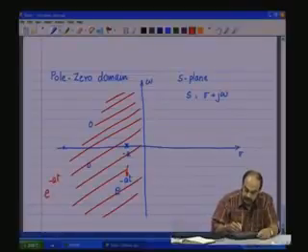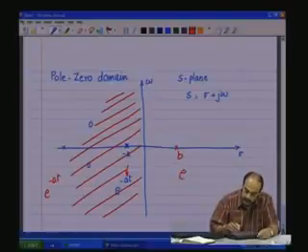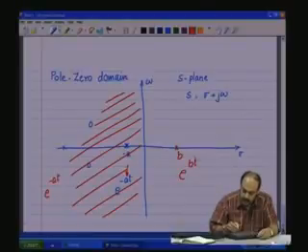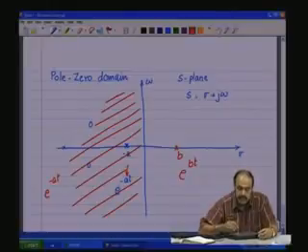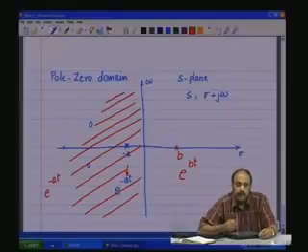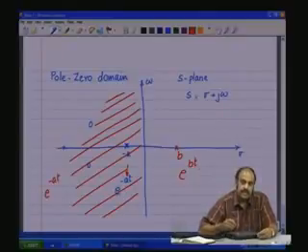But if it is on the right of the S plane, let us say a point b, then it would have a time domain response e to the power of b t, which means it is growing with time. Any disturbance will not decay, but grow with time, as b is positive and it is an unstable system, and therefore, it is not a system which can exist in nature.